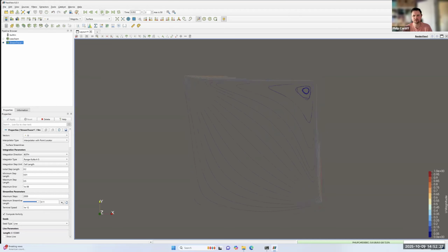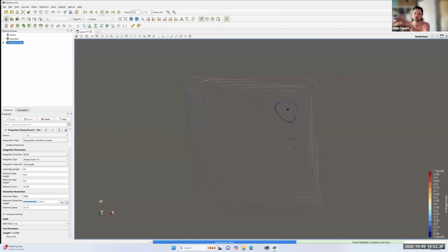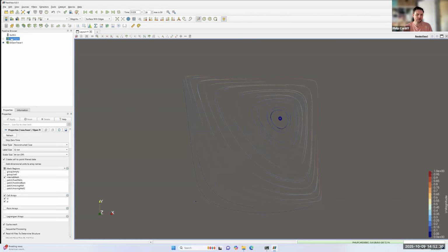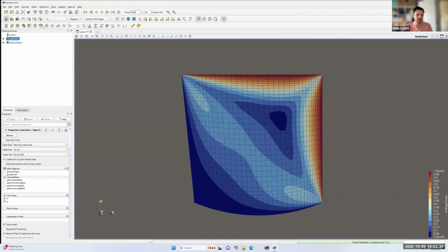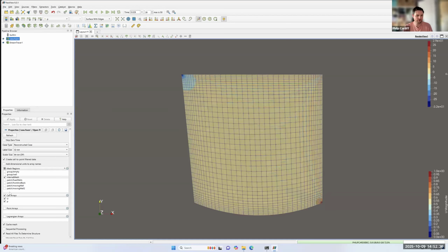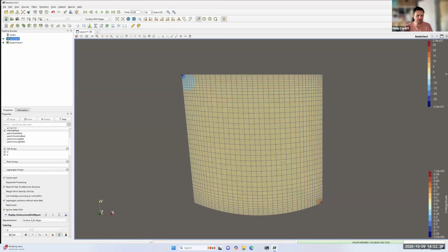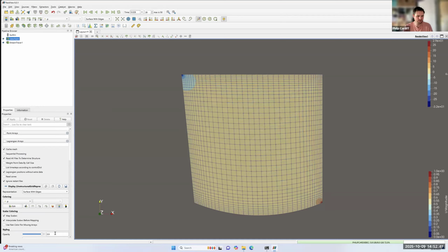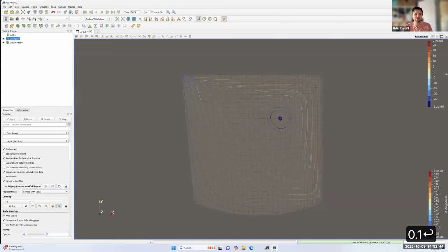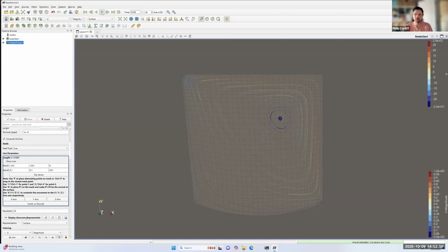Okay. If I color those by velocity, let me jump back to the start time and play it. You see these streamlines, a small vortex starts in the top corner and then starts to propagate outwards. And like in previous cases, you could turn this back on and show the pressure field at the same time and change the opacity, something small, 0.1 is fine. Now you can see both of these at the same time, and for the streamlines you could also use tubes to visualize them. You can see it developing, and you might even start getting a small vortex over here rotating in the opposite direction.